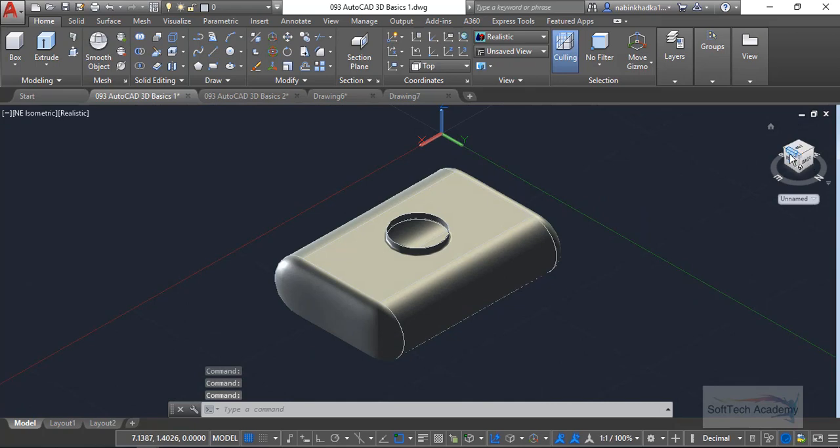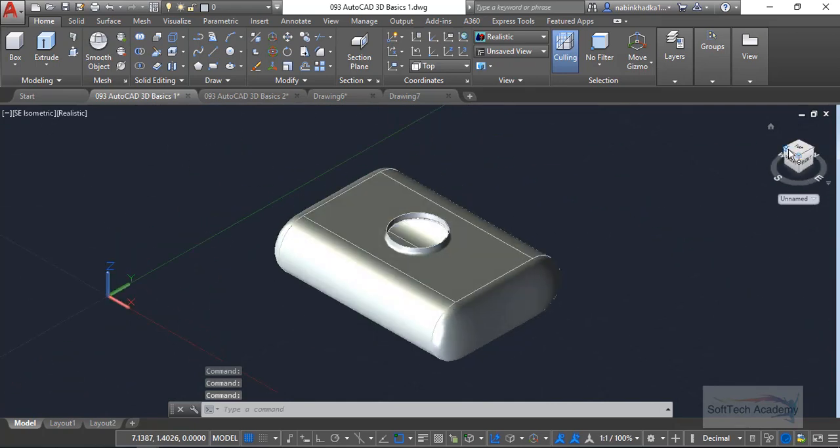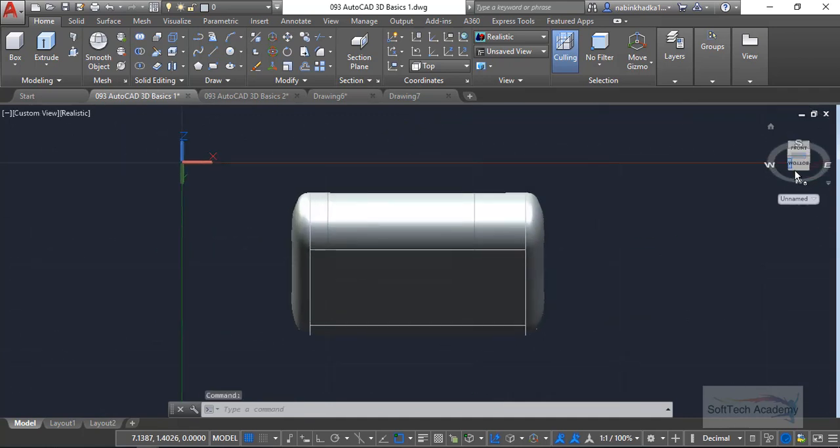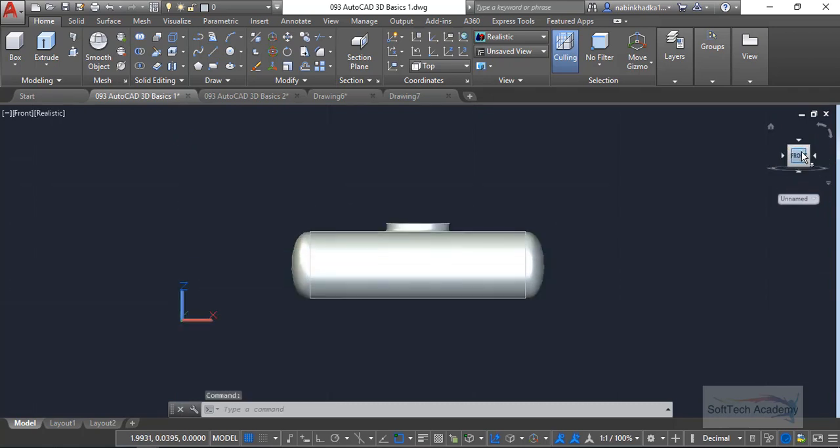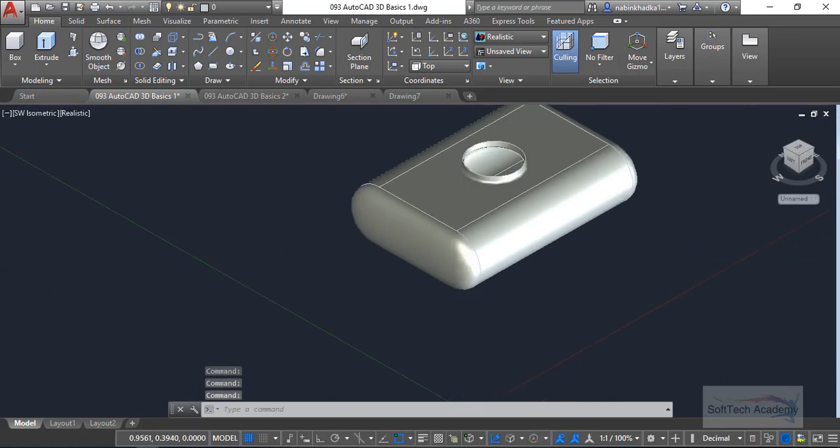By clicking in the upper sections of the cube, you will see the same 2D view, and on clicking this section of the ViewCube, you will see the isometric views similar to southwest, southeast, northeast and northwest. By clicking the lower corners of the cube, you will see the same views but from below. There are a total of 26 views, and a compass that will rotate the ViewCube. So let's make this 3D isometric view.